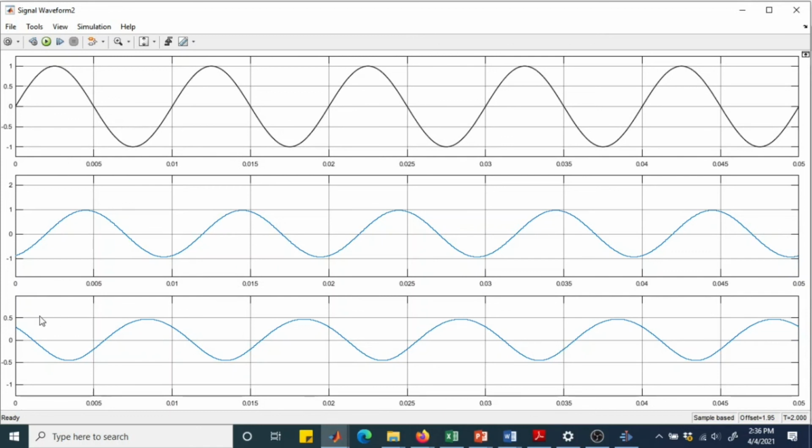So you can observe that in the envelope detector method, the phase shift is quite high. Previously this was the message signal, but because of the low pass filter we have this phase shift. But in the envelope detection we have two different types of filters. The first filter is used within the envelope detector and the second is outside the envelope detector. So hence we have multiple phase shifts. So that is why, when we receive this message signal, the peak is basically shifted or delayed quite a lot, but it is consistent, that is we have a linear phase delay.